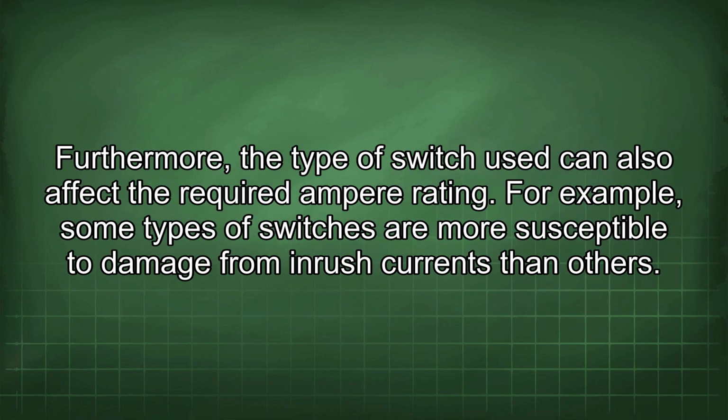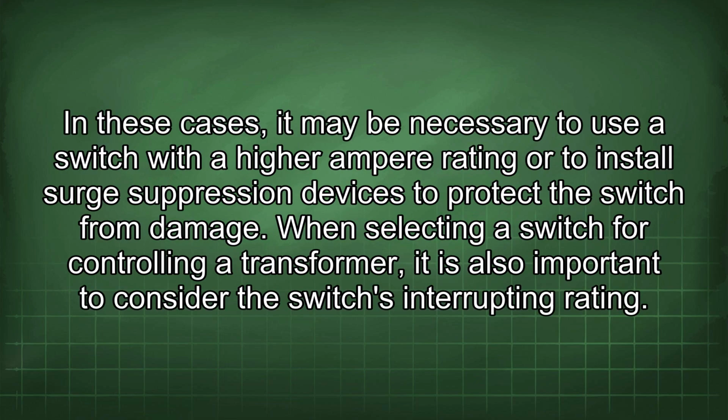Furthermore, the type of switch used can also affect the required ampere rating. For example, some types of switches are more susceptible to damage from inrush currents than others. In these cases, it may be necessary to use a switch with a higher ampere rating or to install surge suppression devices to protect the switch from damage.